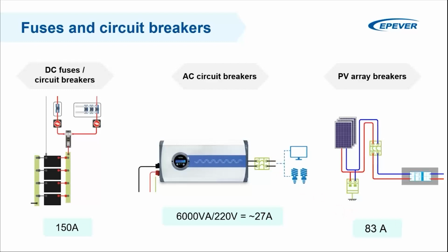And it can be a single pole or double pole. Normally we use double pole for AC. And we also discussed the current rating and the speed of blowing. It should be a fast blowing breaker here and on the input side as well.